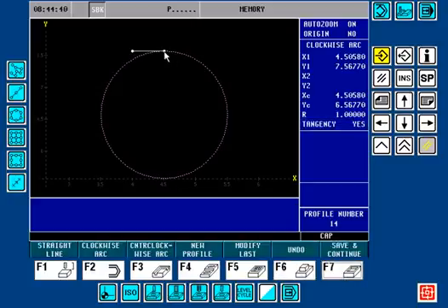This time it turned it to a dotted white line. The dotted white line means that it has some incomplete data in it, and the following element that's going to come tangent off of here hasn't been decided yet. So this circle will be trimmed eventually to the tangent line that comes off of that.